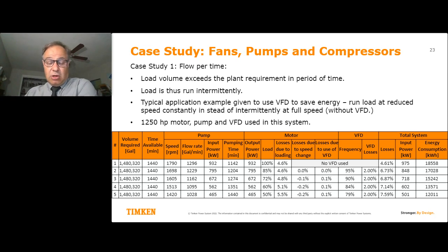So my total system losses have gone up as a percentage. It's gone up to 6.73%. I should not be surprised. The VFD has got 2% losses. But did it make sense? Now my input power is 848.